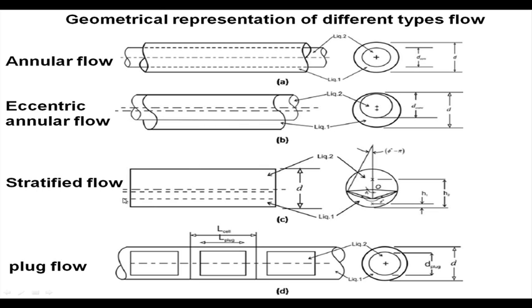Now, as we know, as we increase the conduit diameter more, there is a tendency of stratification. What happens under that condition? The organic phase starts touching the upper wall, and then the entire conduit is divided into two areas, where the upper portion is occupied by the lighter phase, which in liquid cases is usually the organic phase, and the lower portion is occupied by the aqueous phase.